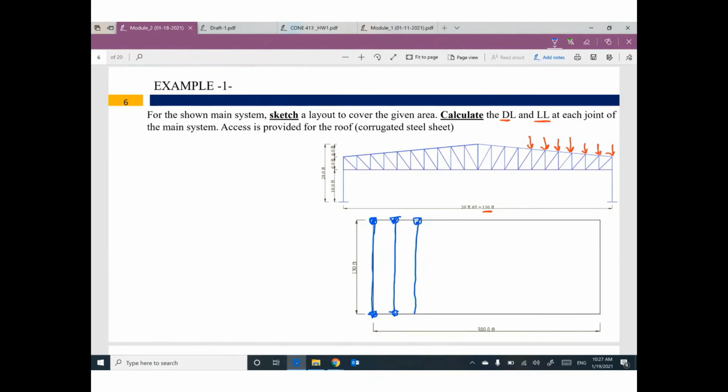I have a question. What is your choice for spacing S? We have a range between 15 and 30 feet. I would like to choose a value that gives me equal spacing. We have 300 feet long, so probably I will use 30. That's fine, or 15, or 20, or 25. All of them will work. Okay, 30. What is the distance A? It is given, 6.5.